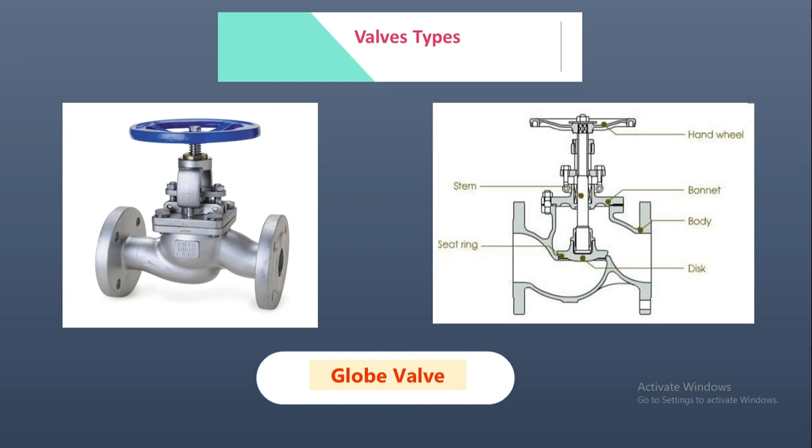The advantages of globe valves are: number one, good shut-off capability. Number two, moderate to good throttling capability. Number three, shorter stroke compared to gate valve. Number four, available in T, Y, and angle patterns, each offering unique capabilities. And number five, it's easy to machine or resurface the seats. The disadvantages of globe valves are: number one, higher pressure drop compared to gate valve. And number two, requires greater force or a larger actuator to seat the valve with a pressure under the seat.